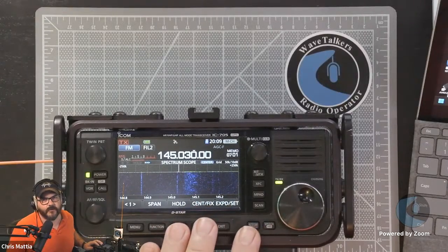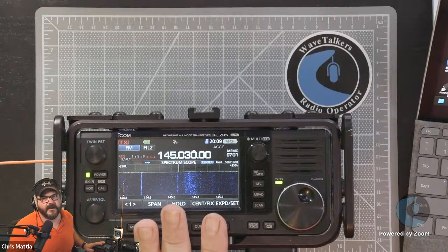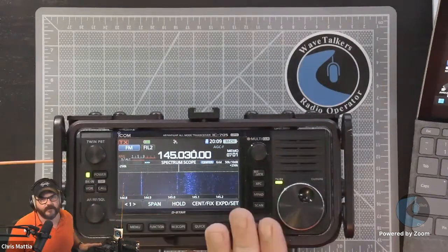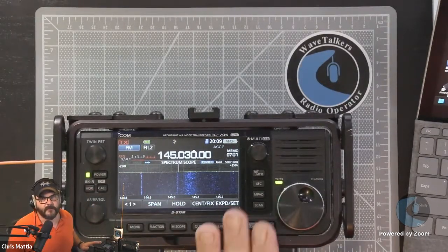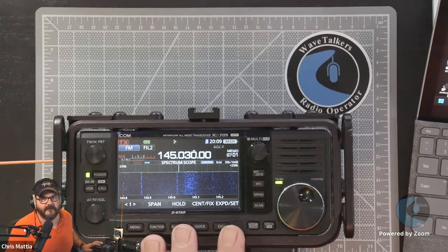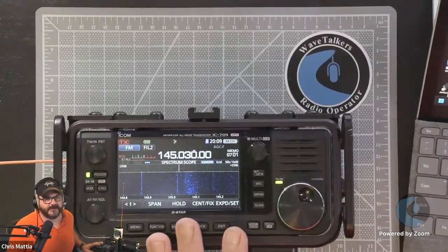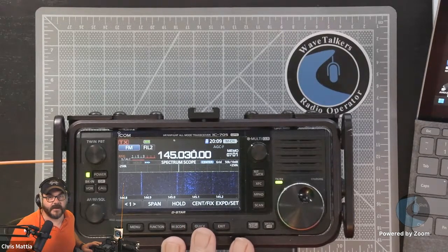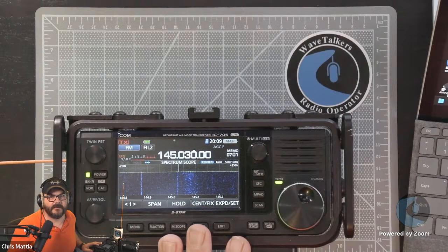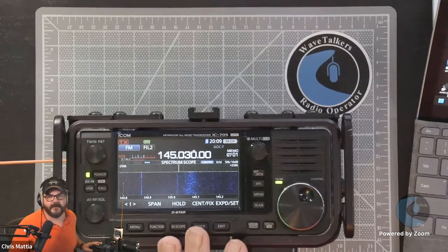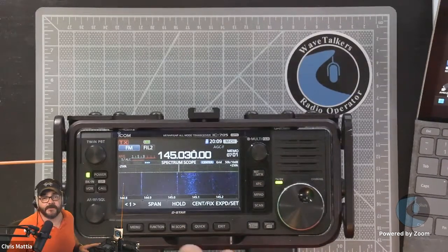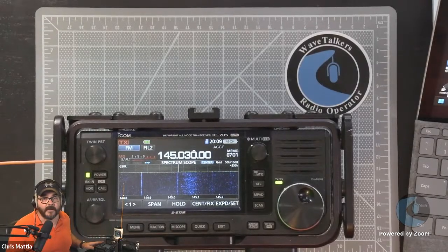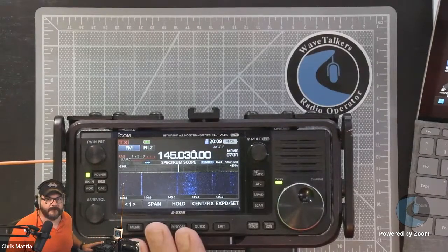I can do all the HF work that I need to do, VHF, UHF. If you're doing things like SHARES or MARS, you can do the MARS mod on it. I have mine that's been modded, so I'm able to pass traffic with whichever mode that I need to when I'm operating with this radio, and it works extremely well for all of that. And a lot of people would kind of worry about whether or not I had the ability to do 100 watts. Well, I have an external 100-watt amplifier that I can plug into this radio. It's super flexible with that.